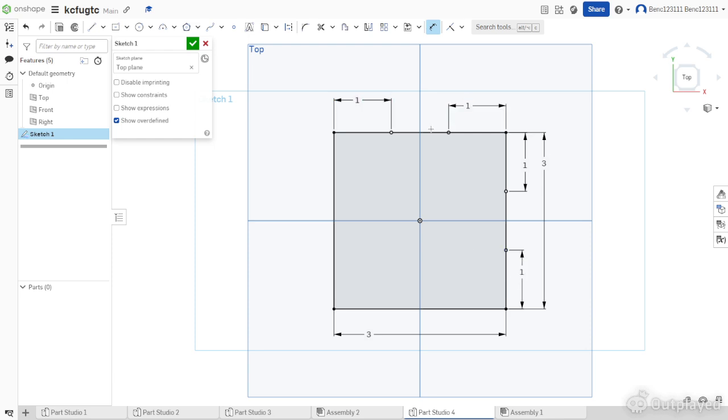And then from here you can see, since we have a total of 3 long, as this down here, and it's a 1 and a 1, there will be 1 in between. This will make sure that you have it at the correct points. Then from here you want to take a line, and from the top point draw all the way down, making sure it snaps with the yellow lines. Make that 3 long, as you can see, 3 over here. Repeat that for all other points. Make sure the yellow lines snap.